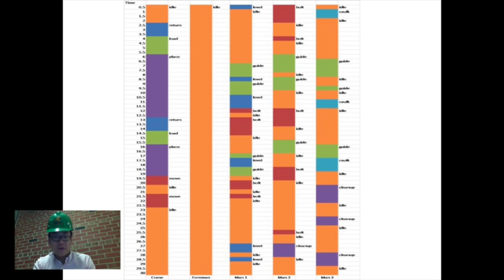Cycle times are not very reliable for this particular chart because the crew has to readjust the wall segment after placing it, and because wall segments are placed at different positions on the job site. However, we can easily see the inefficiency of the work time. There's a significant amount of idle time from all workers and the foreman, which is shown in orange on the crew balance chart. Some of the idle time is built in due to the cycle time of the crane, but